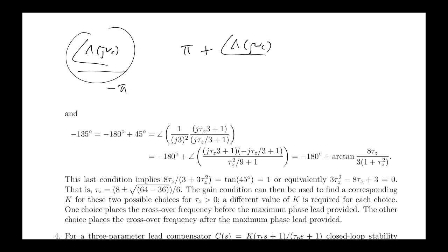In fact, we're trying to see how much above it is. So if we want this to be equal to 45 degrees, so make this 180 so that everything's in degrees. You've got to make sure everything's in degrees or everything's in radians. You've got to pick your units and stick to it, right? So what's written down here in the solutions is in degrees, so let's stick to degrees. So we've got to measure the phase in degrees.